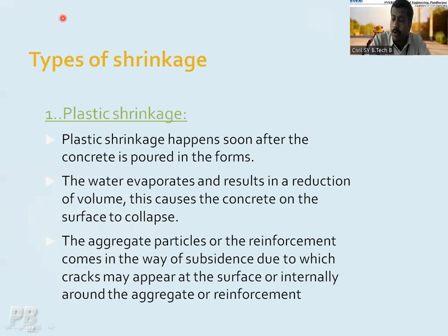So coming back to our point of discussion, now you have started your own project, and one day you are just filling the concrete in maybe a column, beam, or slab. It may be any structural element. So immediately after pouring the concrete in your structural element, what happens? Maybe due to a rise in the temperature, the water starts evaporating from the concrete body itself, and this causes the concrete on the surface to collapse.